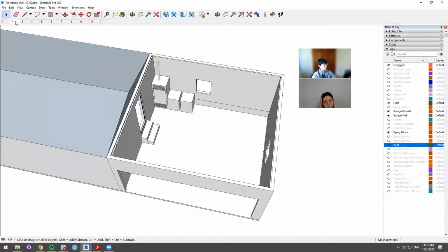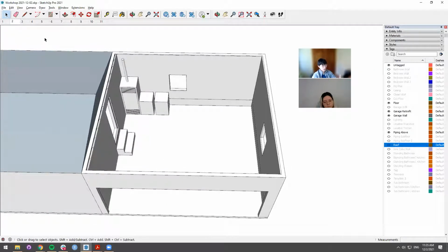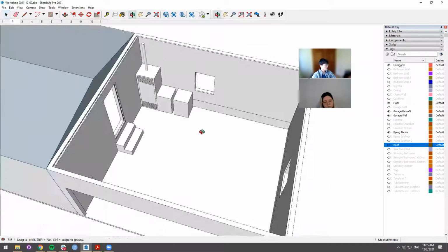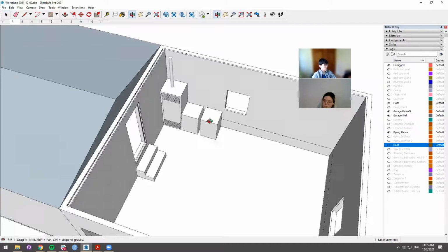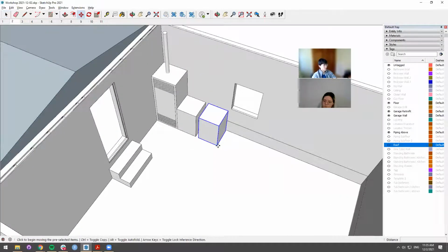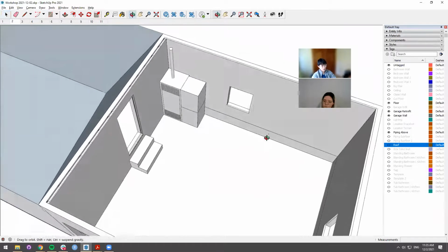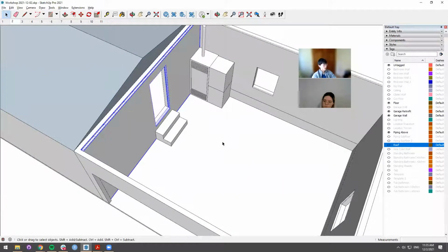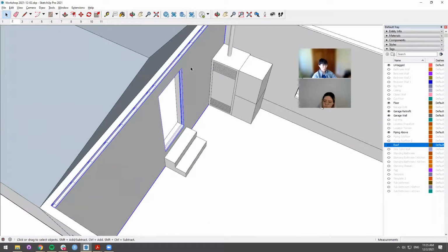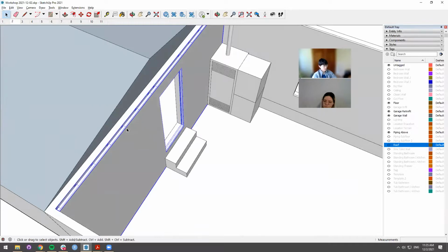So the first thing would be kind of retrofit and then refinishing the existing garage. This was a step I described as, quote unquote, preparing a blank canvas. So things that have happened here are, we might have enclosed the water heater for aesthetics or for venting purposes. We might hook them up with a brand new, stacked washer dryer combination to give a little bit more space in a very, very scarce resource in this garage. And then on the separation wall between the garage and the main residence, remember, which by building code is required to have that fire rating and that sound rating, we've implemented that shaft wall system, which I think is about 3 or 4 inches extra thickness.